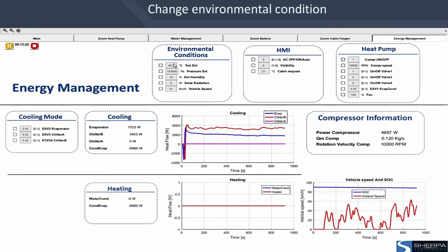Until now, the platform was running using predefined scenarios. These values can be overridden by ticking the box next to the value we want to override, like this. The same can be done using control parameters such as valve opening parameters. Here, 0 refers to a closed valve, while 1 refers to an open one. Values in the middle can be used to quantify how widely open the valve currently is.